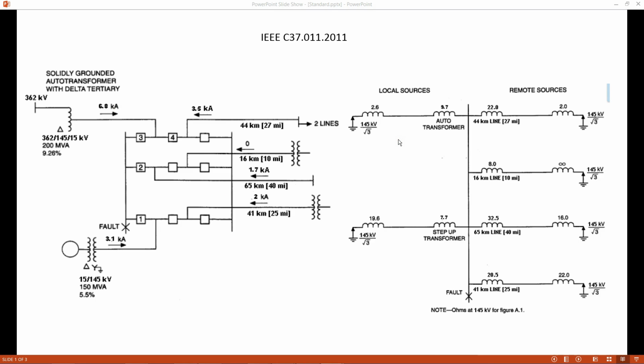So for that, we will choose a breaker which has a certain short circuit current interruption capability, and we'll do the comparison. All that first for the terminal fault, and after we'll do the same thing for the short line fault. I remind you again, the terminal fault is used to identify the worst overvoltage, the short line fault, the worst rate of increase of the voltage.